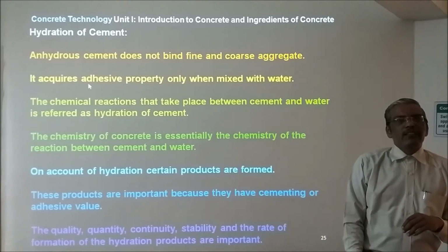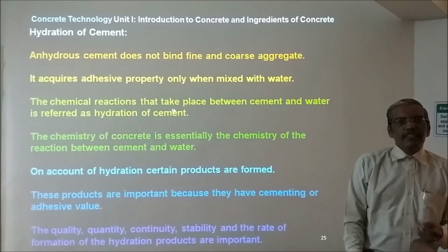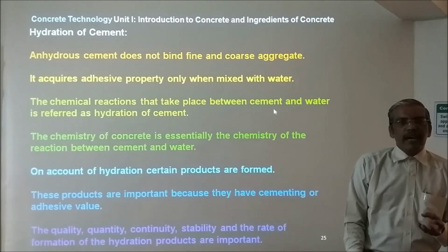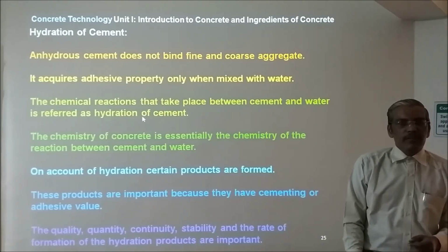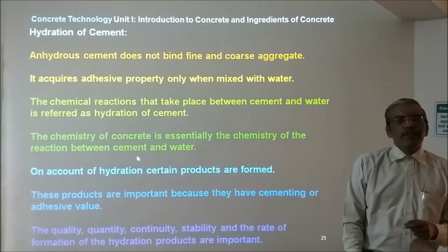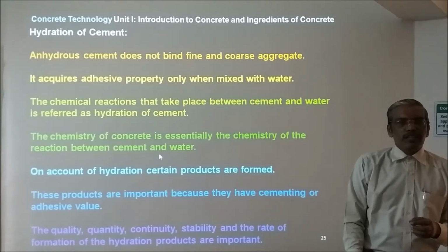It acquires adhesive property only when mixed with water. The chemical reaction that takes place between the cement and the water is referred to as the hydration of the cement. The chemistry of concrete is essentially the chemistry of the reaction between the cement and the water.